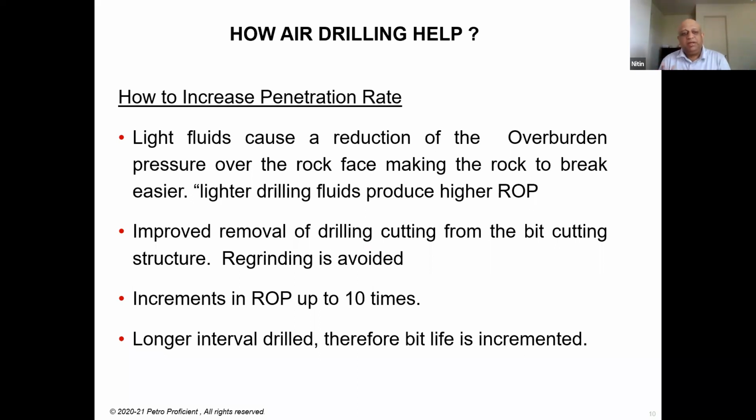Now, we all know that drilling fluid density is always designed to prevent any influx from the wellbore. Here we are talking about drilling through a section, through areas which are non-hydrocarbon bearing. Plus, we have surface equipment such as a rotating control device, and we will see that in our coming slides.